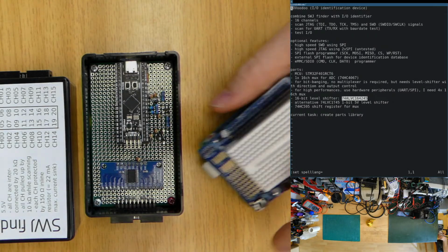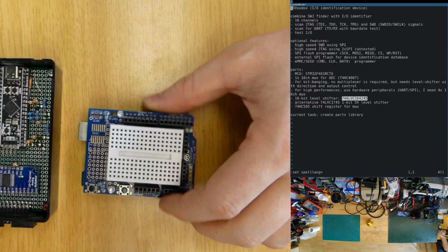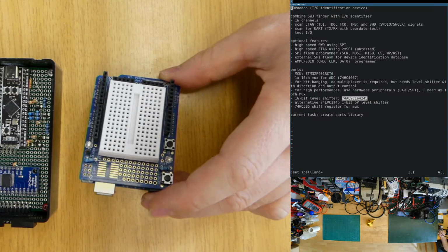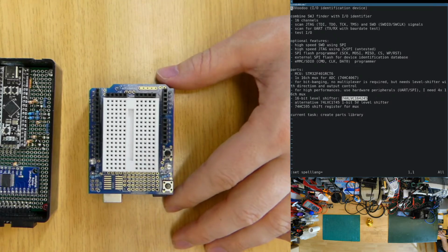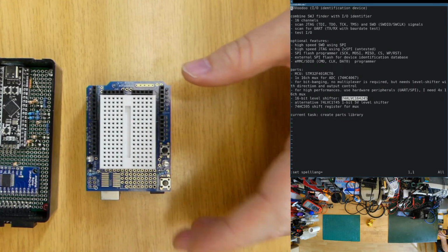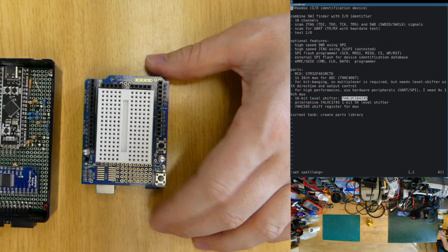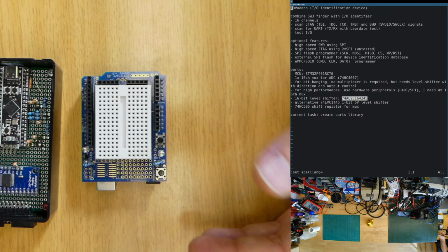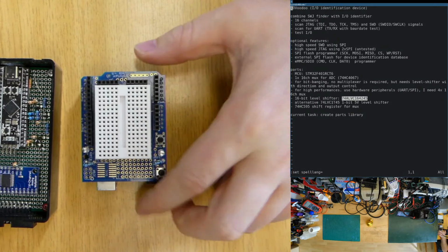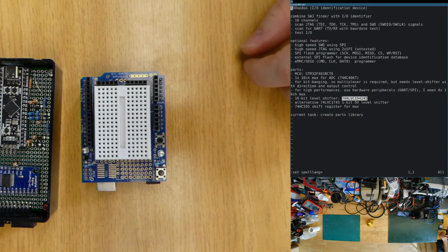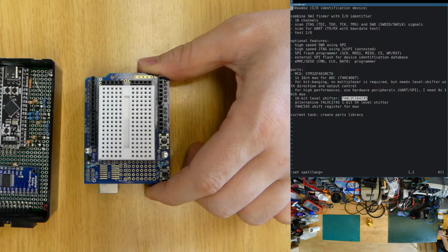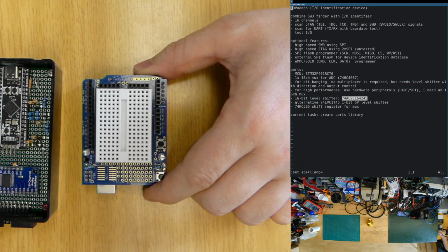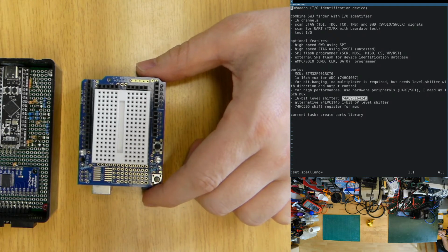For example, if you still have one of those Arduinos, this is an old Arduino, but there are still enough Arduinos which use 5-volt I/O lines, for example, for UART, and you still want to scan UART. So there are still some old microcontrollers which use 5 volts. And whatever you're reverse engineering, it might use that. This is why I want 1.8 volts to 5 volt compatibility. And for that, I need a logic level translator or voltage translator.